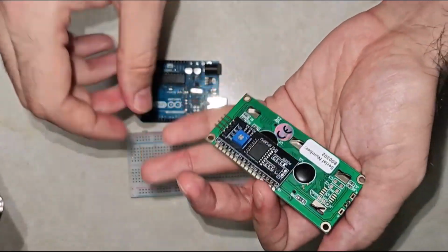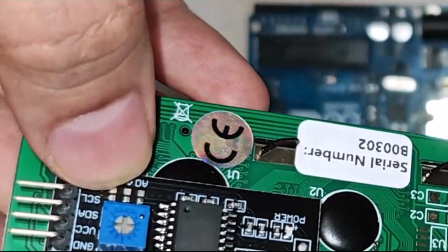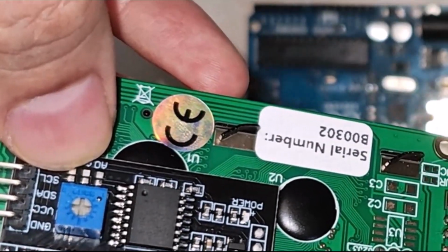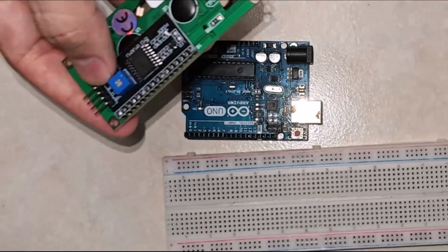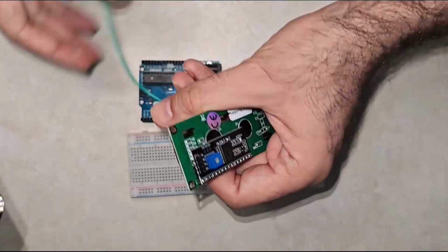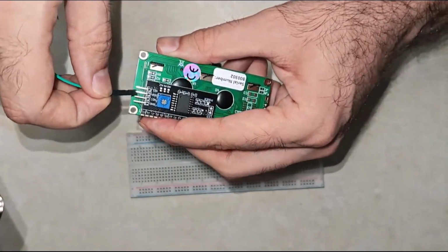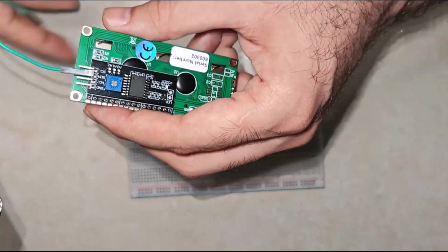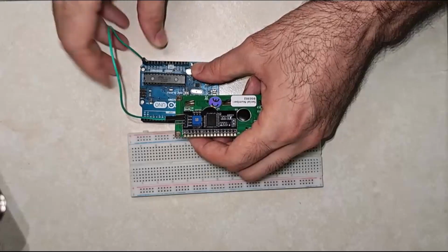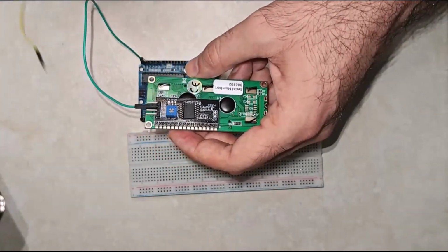Okay, so as you can see here in the 4 pins, SDA and SCL, we connect the SDA to A4, and we connect the SCL to A5. Let's just connect it, guys. So this is the SDA. I said let's connect it to pin, for example, A4. Okay, so A4. And this is the SCL, the last pin.